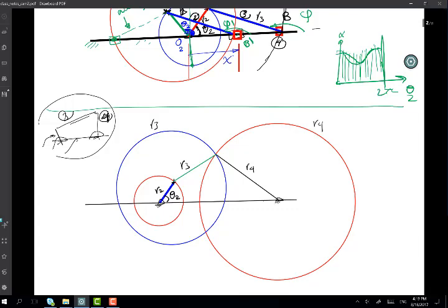For a given value of theta 2, whatever value, find the angle of link 3, theta 3, and the angle of link 4, theta 4. So you're being asked to calculate those angles, theta 4 and theta 3. All right. So just now, as simple as I've done it, it's just a matter of intersecting the circles.